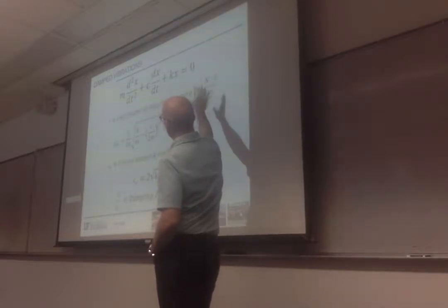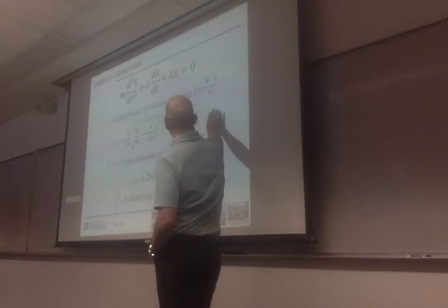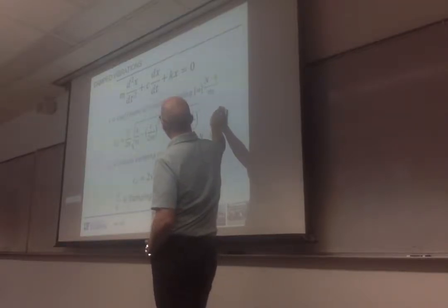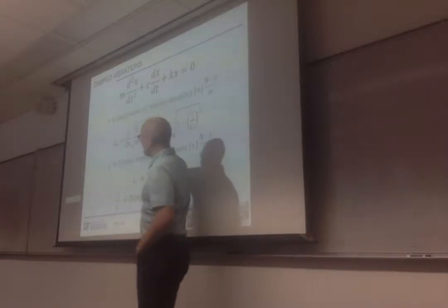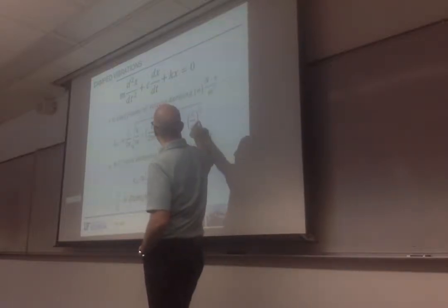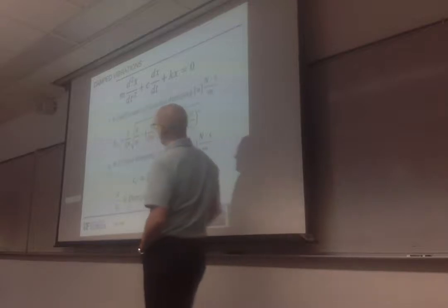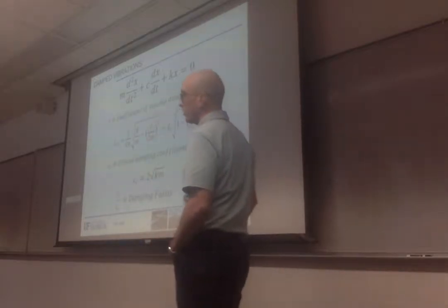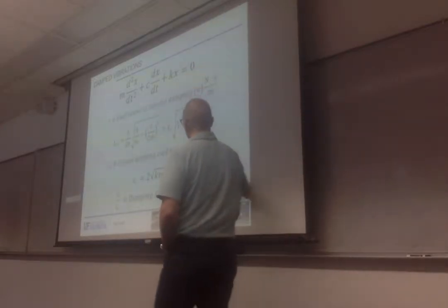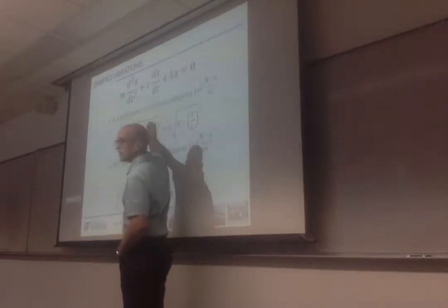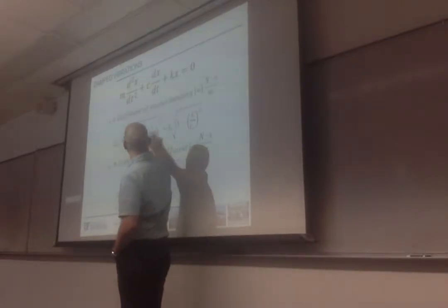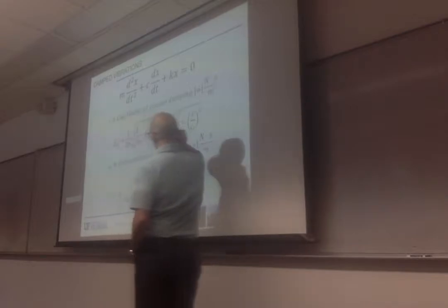If we were to solve this equation like we have done in the case of free vibration, we will end up with a frequency for that vibration that is a little bit different than the natural frequency of an undamped vibrating system. The difference comes in that second term under the square root, where the damping is involved.